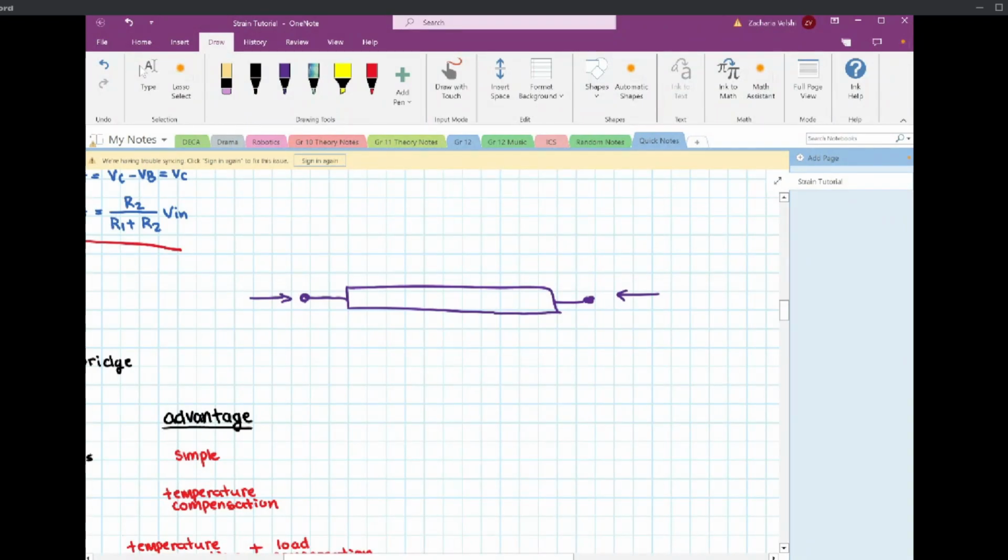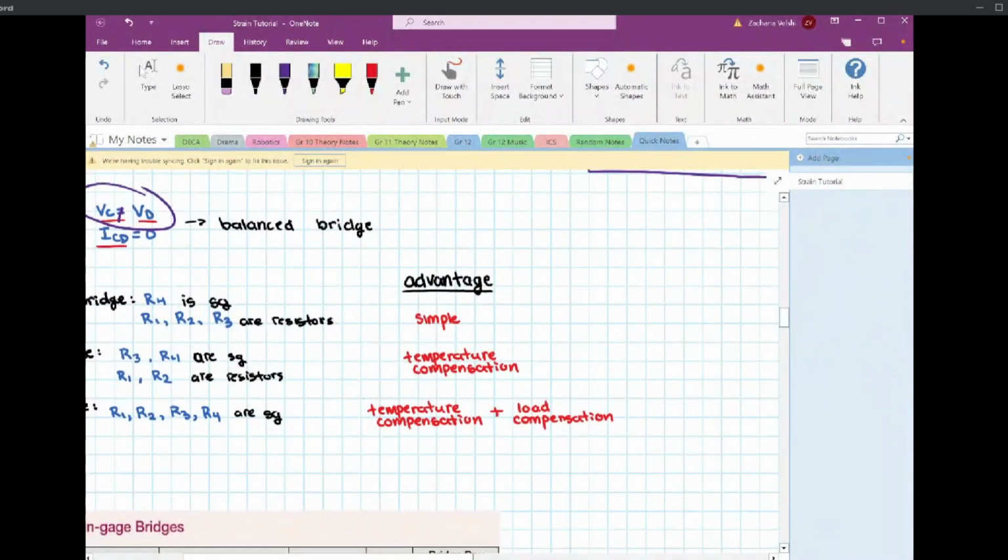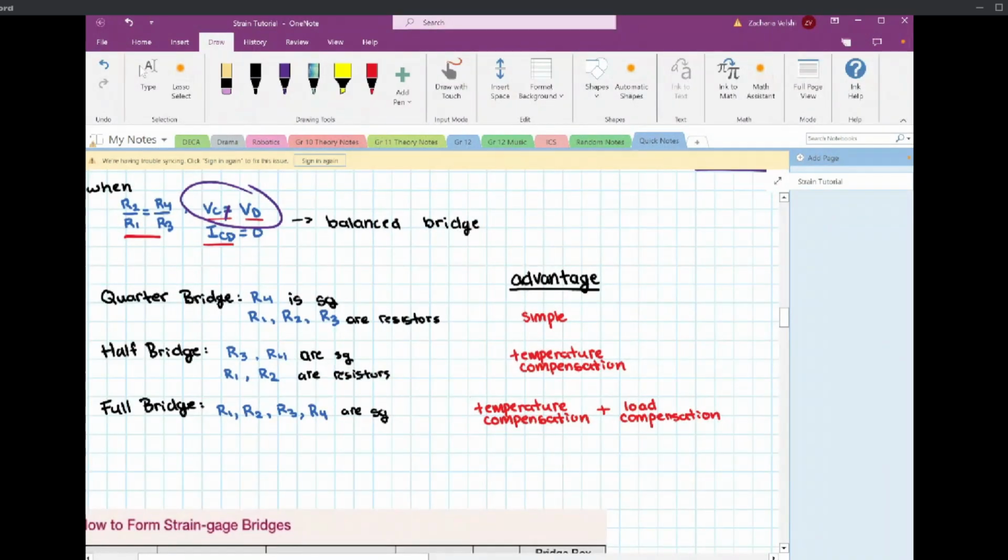You only want to see the axial loads, but all of a sudden you get rammed from the front, like you hit a tree, and you get a big bending load. I didn't want to see a bending load or how much force that caused. I was expecting the tie rod to fail in axial loading, not bending. I only want to measure the forces in the axial direction, so I don't care about these forces. You compensate for that by making a full bridge.